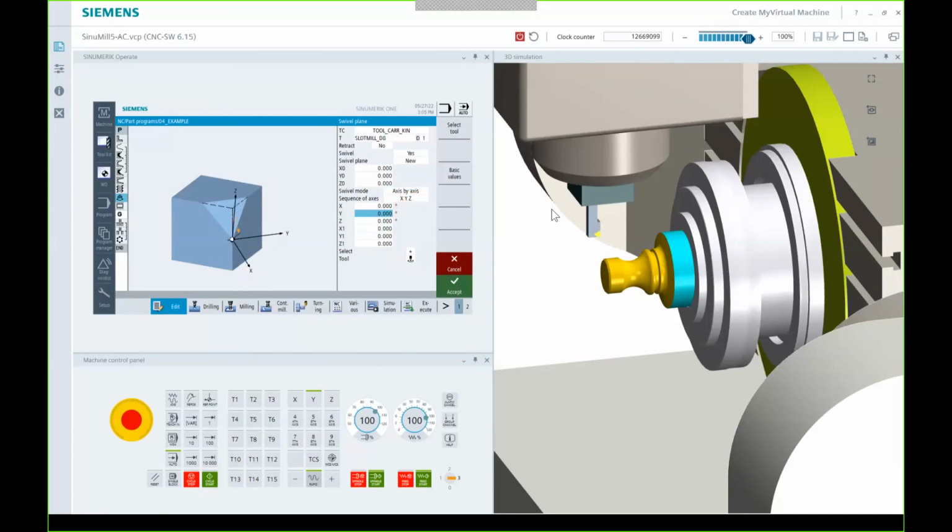It'll move my C and my A to give me whatever angle I was trying to get in the Y, because that becomes a 2-axis rotation. And then I have a last minute little datum shift. After everything's rotated, I can move my 0 around. And then when that's all done, that now becomes the new 0 of the machine. In this case, I want the machine to go back to G17.